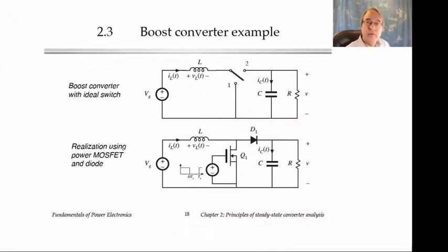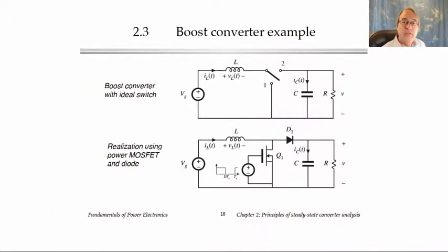Work a boost converter example. So we're going to apply the techniques of volt-second balance, capacitor charge balance, and the small ripple approximation to find the voltages and currents of the boost converter. So here I've shown a boost converter using an ideal switch.